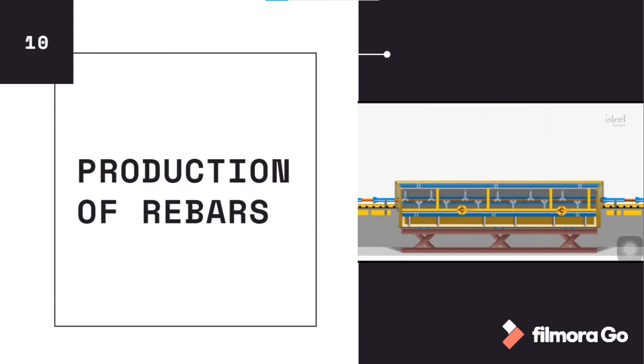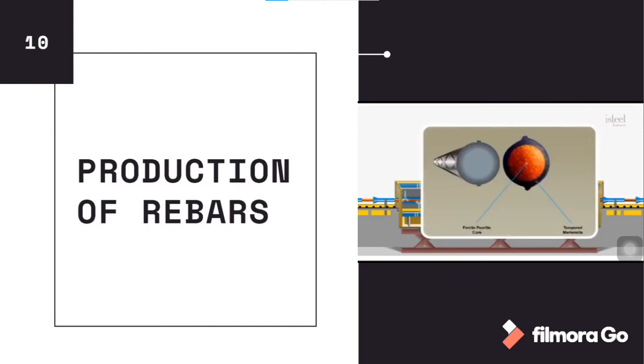It could be Fe 415, Fe 500 or Fe 550 grade. This forms the hard outer layer called tempered martensite and soft inner layer ferrite pearlite. The outer layer is thus hard and keeps the bar strong, while the inner layer, being soft, provides flexibility and elongation.